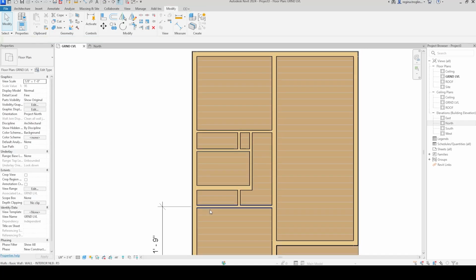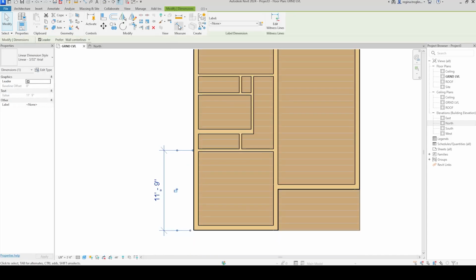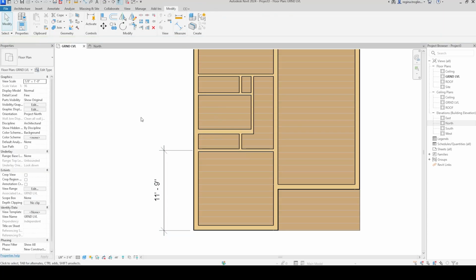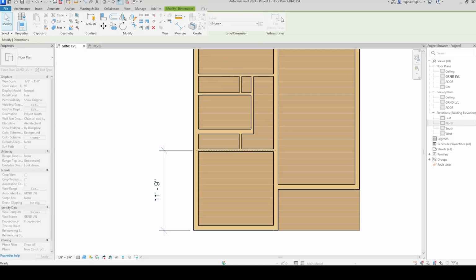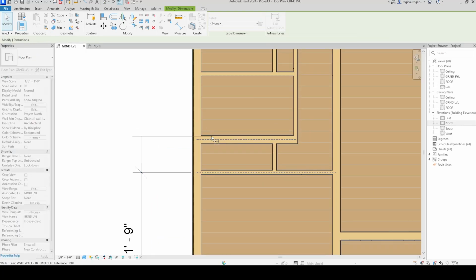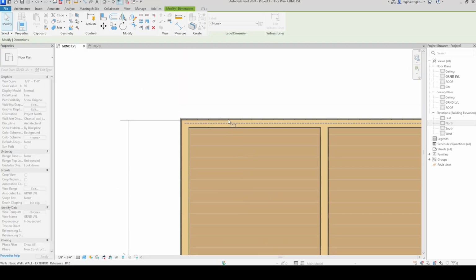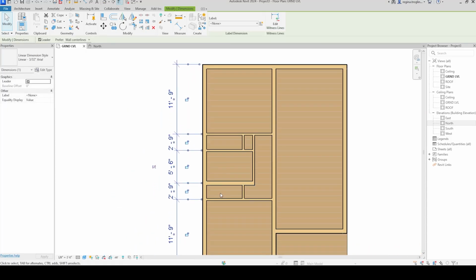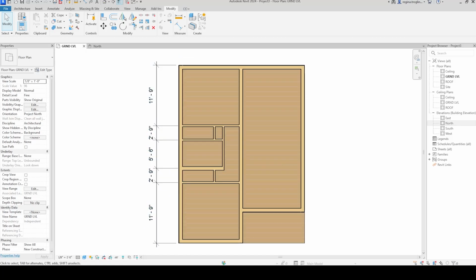The other thing is having this closet in place in the proper location. And we will go ahead and finish dimensioning this one side. So grab your main dimension that you had made before. Do an edit witness line. So it's going to go wall center, wall center, wall center, wall exterior. There we go. So these top two and these bottom two should match what is on plan. If they do not, make the adjustments.